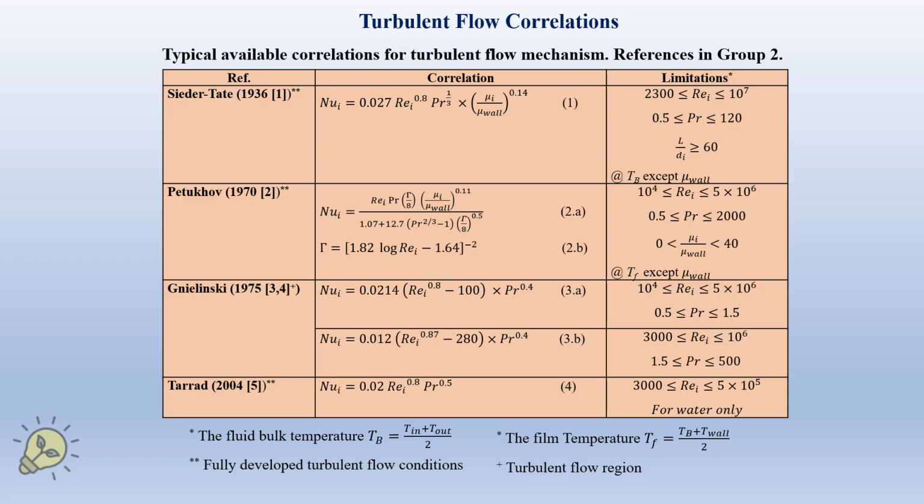And the film temperature depends on T wall plus T sub B divided by 2. These correlations, of course, require the knowledge of the thermal properties of these fluids. We are going to use one or two of these correlations in our present application.